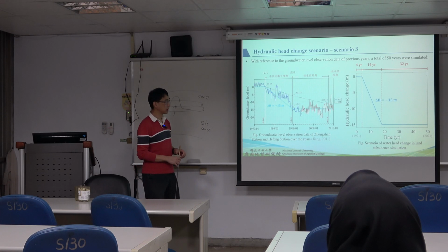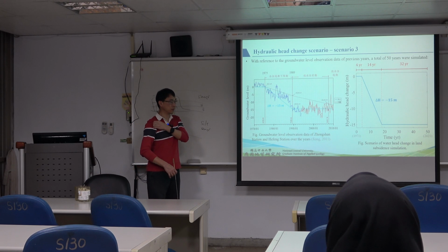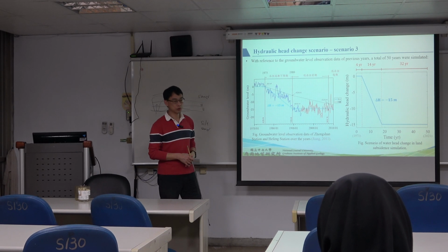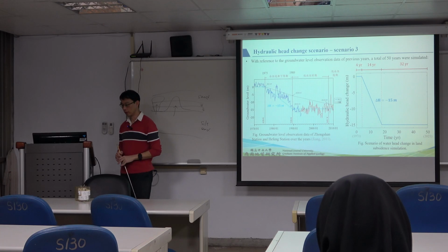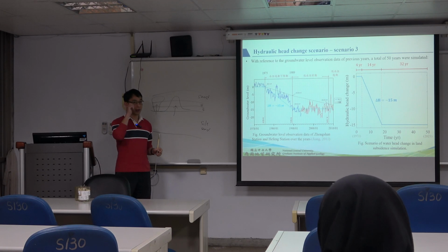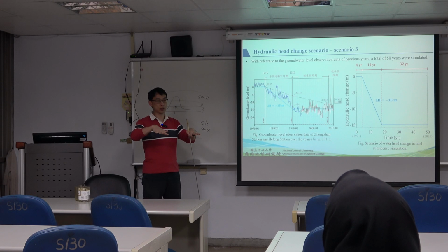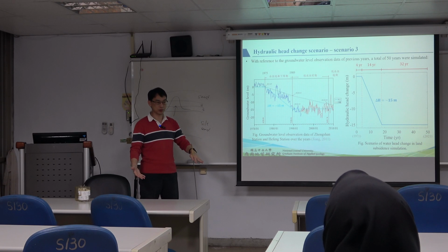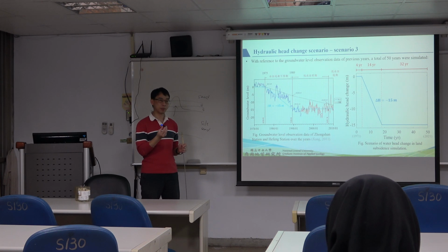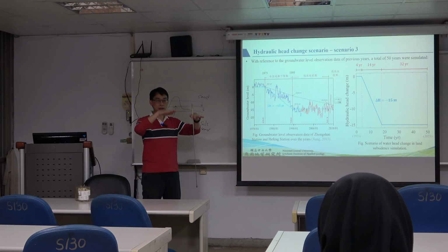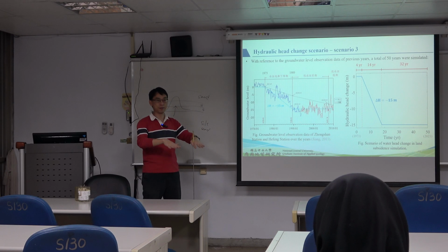So the driving force in these models, we use a uniform, the same decline of the head. We do not use pumping. We use the head to control the pumping conditions. We know that if we would like to assess more completely, we might use pumping, and then pumping induces the decrease of water level, and water level decrease induces the compression. But right now we don't know exactly the pumping quantity, so we try to avoid the pumping settings. We directly jump to the ground levels. We know the ground level observations, right? So we directly assess this ground level decline or uplift, and how it affects the system.